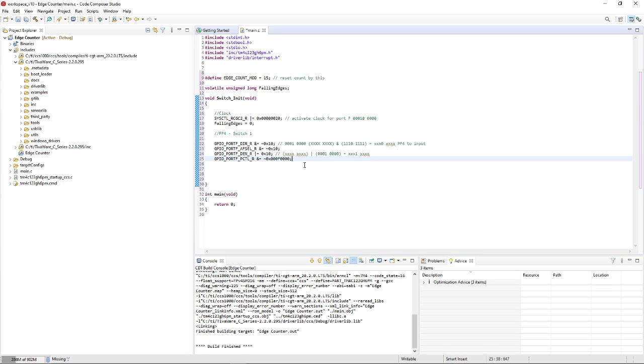And so here we can look at the top. The way that this register is set up is that each of the register locations has a full nibble associated with it. So this is the first nibble, and that's F0. This is the second nibble, and that's F1. This is the third nibble, fourth nibble. Well, 0, 1, 2, 3, 4. You gotta count from 0. So this is the fourth. This is the one associated with F4, and that is setting all of its whole nibble to 0.